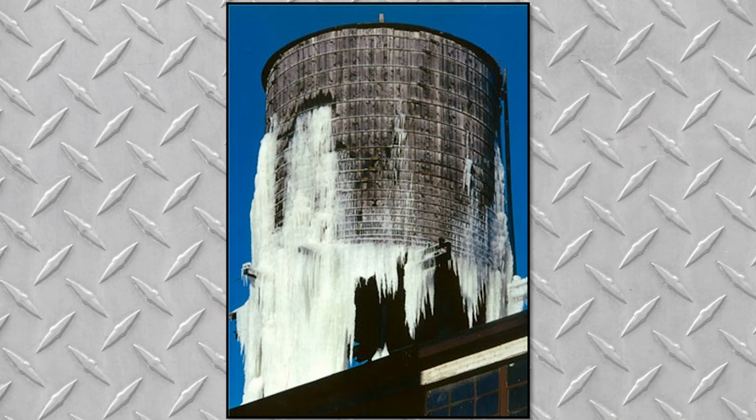As indicated to some extent by this picture of an ice cooling tower, changes in the seasons can affect how you're going to operate chillers or whether you're going to operate them at all. The first thing you should do is determine what kind of seasonal use patterns your industrial facility has for cooling. If it's primarily space cooling, it'll typically be different than process cooling. And sometimes if process cooling is dominant, a chiller operation is not going to change very much in the winter or the summer.